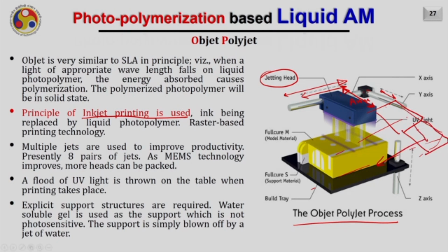So for example, you want to build a part which is something like this, and its length is L, height is H and width is W. Now this is your head and the length of the head is A mm. Now if you want to scan this entire area, of course this head has to be indexed from this position, next to this position and next to this position.